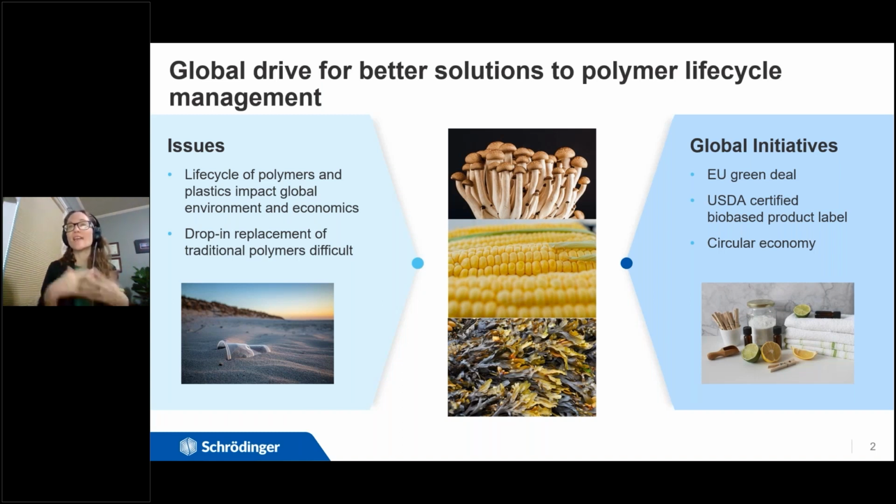And these bio-based materials, when I use that term, I'm using it in kind of the broadest sense of any kind of polymeric plastic material that has some root in a living organism. So that could be from really traditional saccharide-based polymeric materials, where you're using the saccharides that are coming from polysaccharides from natural materials, and then using that to make something new, or using the fundamental building blocks from some of these natural organisms to make new monomers that you can then polymerize and make into new polymers. And all of those have the base in a biological entity that we're kind of reusing in a new way.